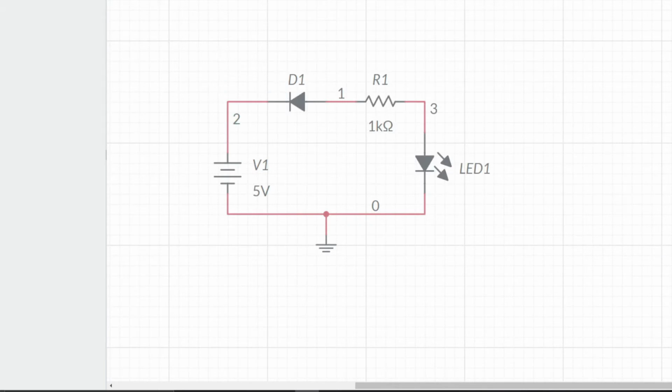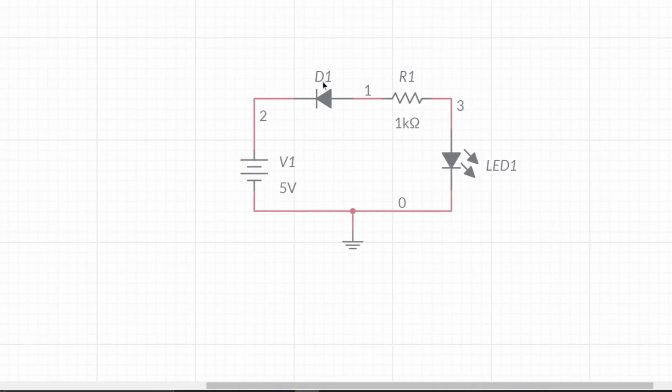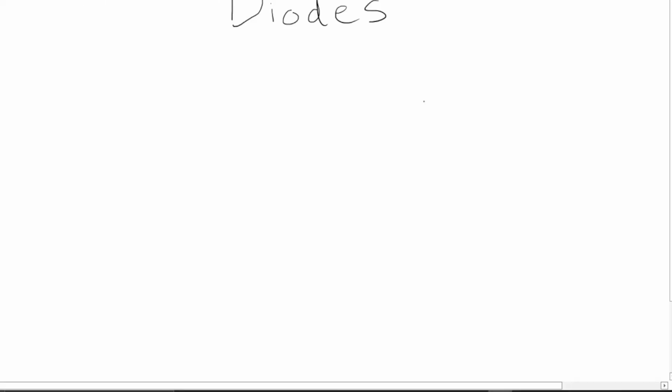So as you can see here, I've put the diode into reverse bias, and as you can see, the LED is not on anymore. This is because, as I said before, the diode only flows one direction. If I put a current probe there, there's basically no current, just picoamps. We can basically say there's zero current flowing because the diode's doing its job. It's doing its job perfectly. It's blocking current. So back to the electronic whiteboard notepad.